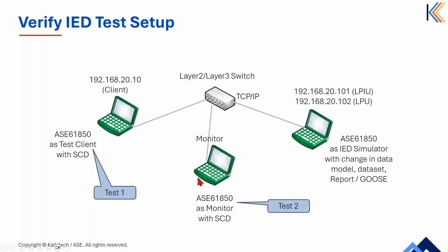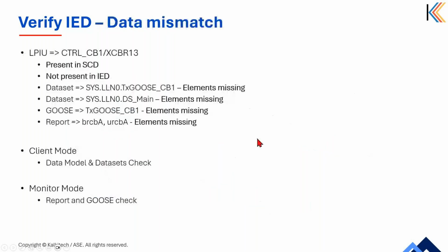So in this case, we will have both client and server running with same modified SCD file, and the monitor mode will have the original file. So that means monitor mode will be expecting certain data points in client and server, and it will look at the report and GOOSE to verify that. So we'll see these two use cases today.